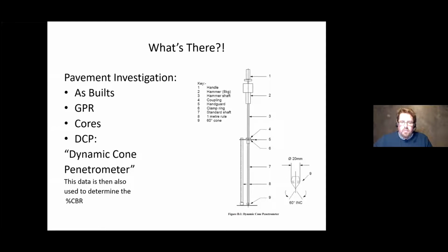It won't go, because we get very well compacted, very good depths of granular material, and this really was designed for subgrades. That said, if you're taking cores, do your DCP. It gives you much more information, because the core will not remove granular material, and it's definitely worth doing for the amount of time that's involved.